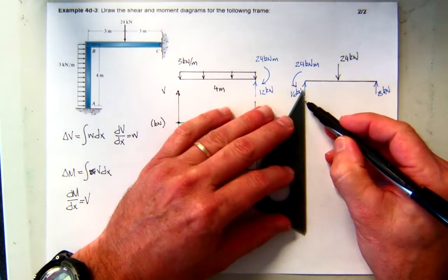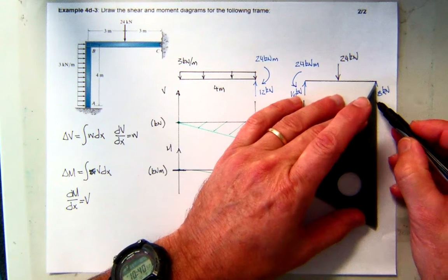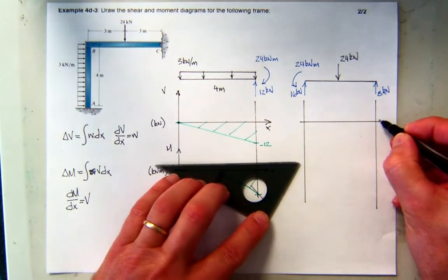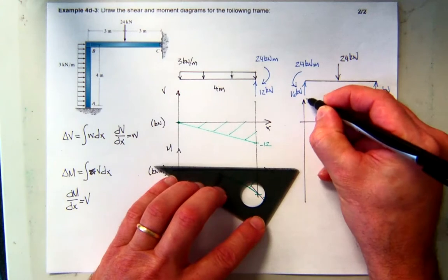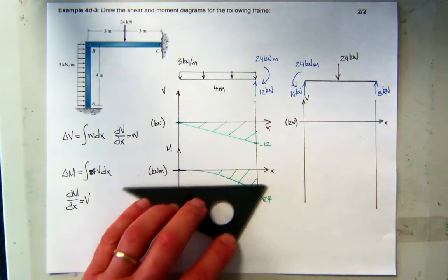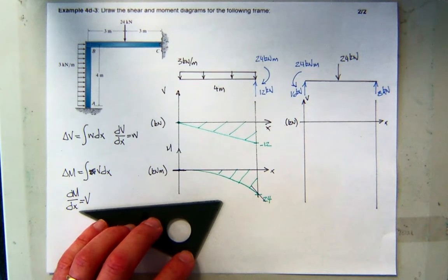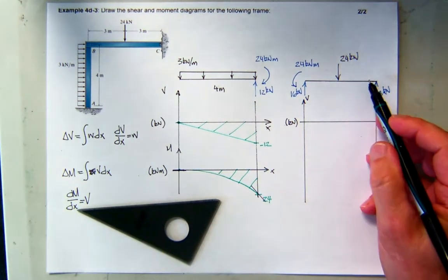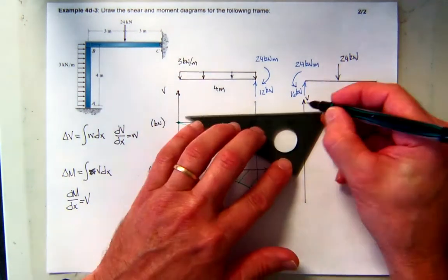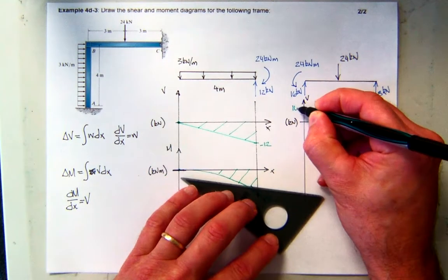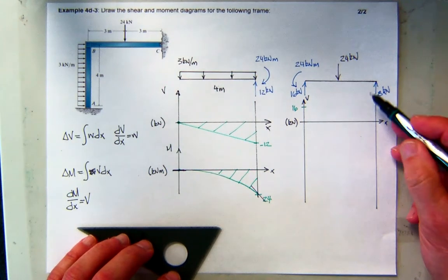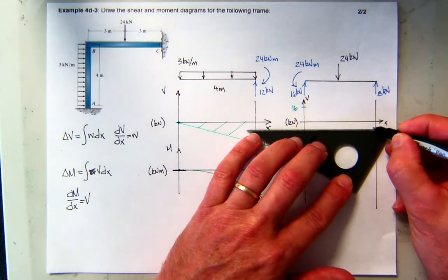So then we can generate a quick template for that one. Beginning and end. Establish an x-axis. Again, positive shear. Units of kilonewton. What is the shear at B on BC? Is that positive or negative shear? Positive. What is the shear at C on BC? Negative 8.